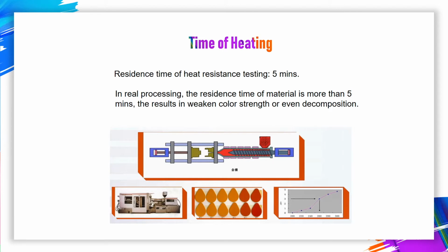Finally, also pay attention when using a twin-screw extruder to produce color masterbatch. In order to improve the production, the length-diameter ratio and the mixing section are often increased, so the residence time of colorant increases too. Eventually, the risk of thermal decomposition of colorant gets higher. As we recommend, preventive measures should be taken to avoid any thermal damage. Moreover, in the twin screw and high-speed extrusion process, the high shear force contributes to the rising of material temperature, which will cause part or even complete discoloration, and also migration, diffusion, and frosting.